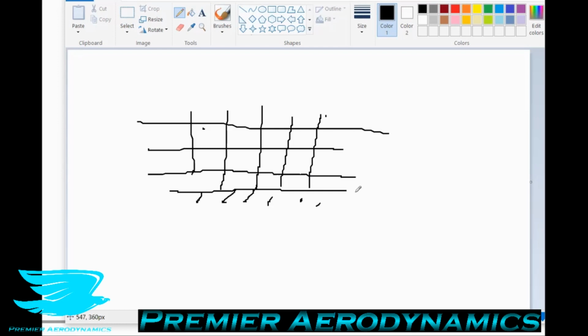The height of this first cell and the second cell, and so on, are very important. This is determining how well the boundary layer is resolved. The boundary layer is very important. Using wall functions allows us to have a thicker first cell, so the first cell height is greater, and not compromise much on accuracy. What we do is use empirical functions, which means we get data from real life and even DNS, so very good CFD, and then we figure out equations that approximate the boundary layers under certain conditions.